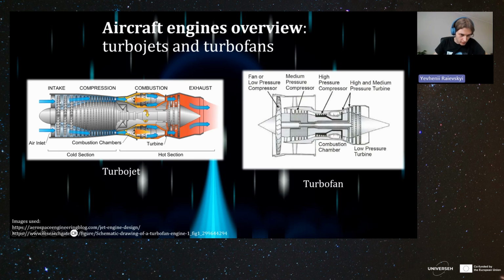Those ones here, and the next ones, they are more and more thin. Those are blades which accelerate our air molecules and then convert this kinetic speed the air molecules have got from the blades to pressure. So this is basically what a compressor does.